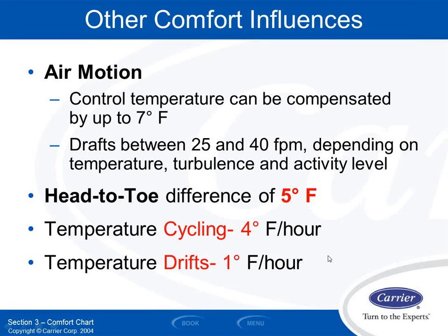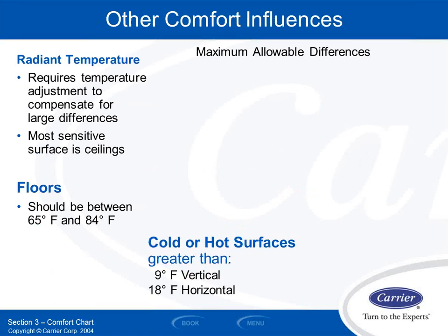From a perception standpoint, almost nobody can detect a 1 degree temperature difference. It's very rare that if you change the room temperature from 72 to 71, someone actually knows that. Most people can't perceive that 1 degree difference, and usually most people can't perceive 2, 3, 4 degrees either. So I can have a little bit of swing in terms of comfort, but it's still got to be reasonably tight.